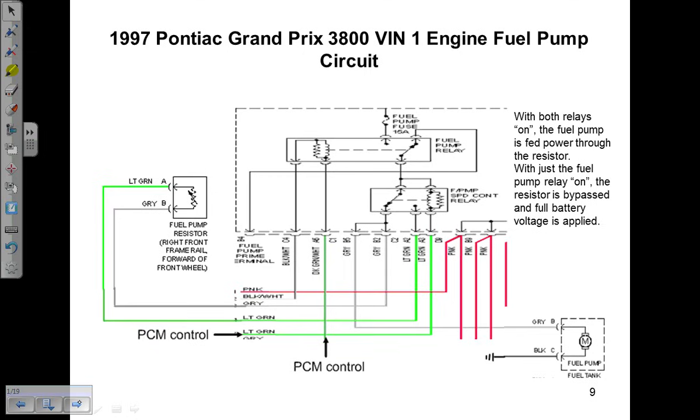So again, same exact symptoms. And this was a car I worked on, got good pressure cranking, but then the car would stall. It would not stay running. Crank it, good pressure, and then as soon as you let off the crank position, fuel pressure would drop down, the car would stall. Same exact thing.